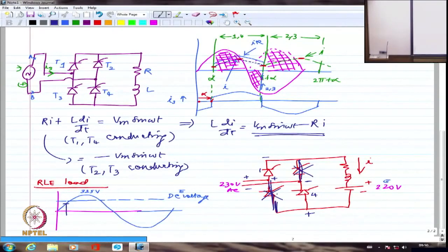I have the supply voltage connected here, which is positive, but this plus also comes into the picture here, because it is open circuit voltage. I have to look at the open circuit voltage. When there is no current, there is no drop, nothing here, so this voltage will appear right there.